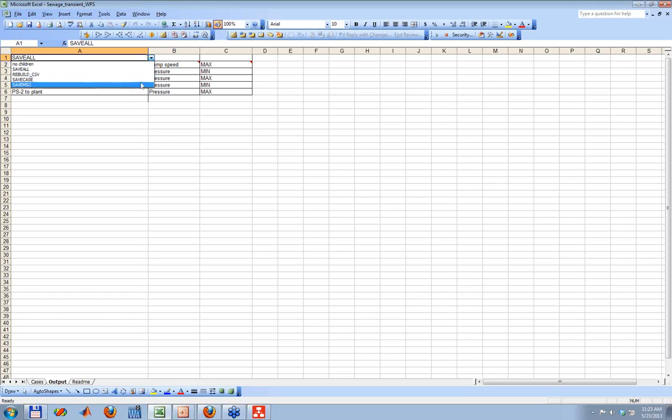Finally, there's rebuild CSV. That's one if you have run the parameter script and you have all the child cases and you think, okay, I need this extra output. I would like to know the extreme pressure on this point. Then you can just include it in this list and rerun it with rebuild CSV. Then you don't have to run all your simulations again.